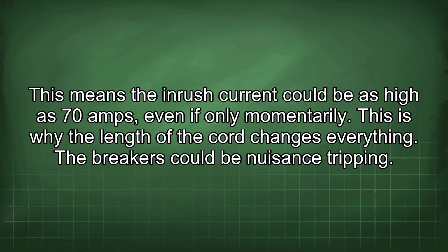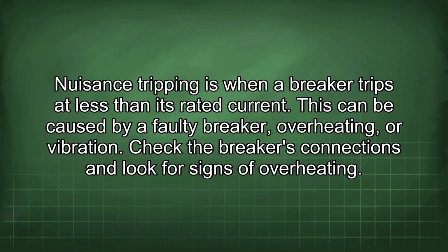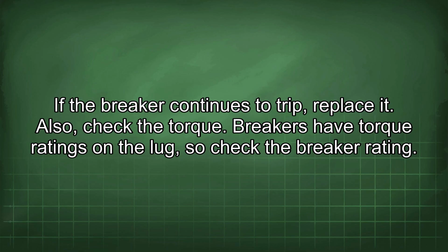The breakers could be nuisance tripping. Nuisance tripping is when a breaker trips at less than its rated current. This can be caused by a faulty breaker, overheating, or vibration. Check the breaker's connections and look for signs of overheating. If the breaker continues to trip, replace it.